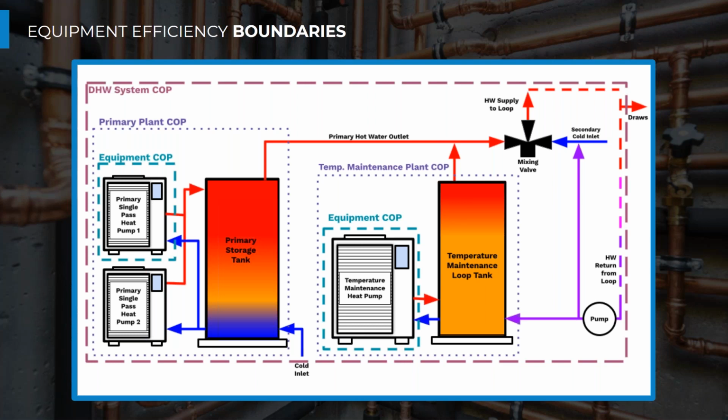But it really comes down to how much of that piping is in unconditioned spaces like the garage. We're putting the heat pumps in the garage, which is beneficial for our 134A technologies. But if we're running a bunch of piping in the garage and it's our big main piping, the garage is typically a cooler environment, and so we're going to see more heat loss there. We also have a lot of clamp supports in that area, so we want to make sure that those are thermal bridge free and not bridging to the concrete.